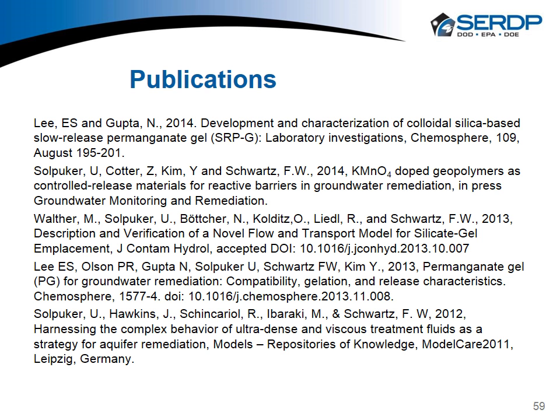Thank you. Frank, I can add a couple things. Okay, sure. You can mix the diluted silicate solution and the acidic solution at the injection point. Or you can first inject the silicate solution and then inject the acidic solution, so the mixing takes place under the ground. That's about it. Okay, thanks. I think that's all we've got on that.